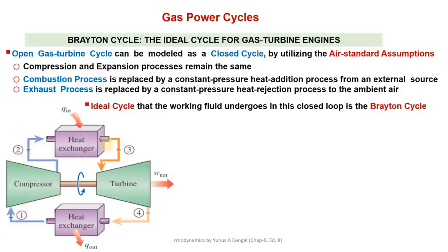So the maximum pressure in case of gas turbines, the maximum pressure means this pressure 1 to 2, and then 2 to 3 pressure remains constant. So here is the maximum pressure in case of gas turbines. This maximum pressure in gas turbines is quite low compared to steam turbine, because in steam turbine we have seen these pressures could be more than 22 megapascal, but in gas turbines the pressure rise is not so huge.